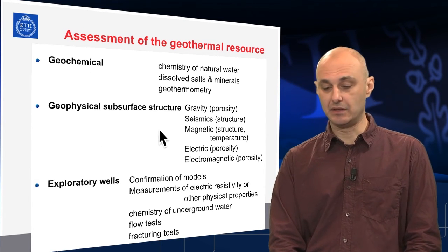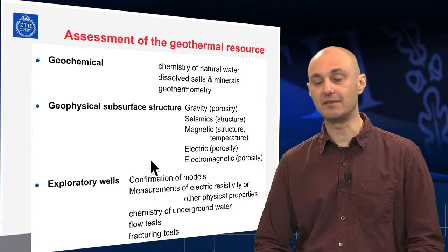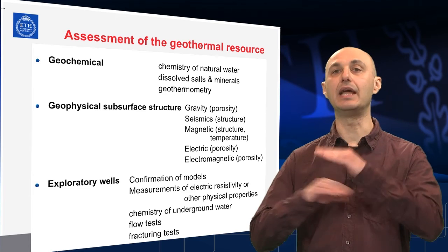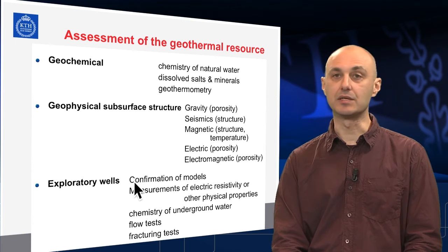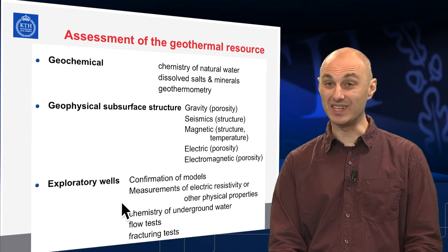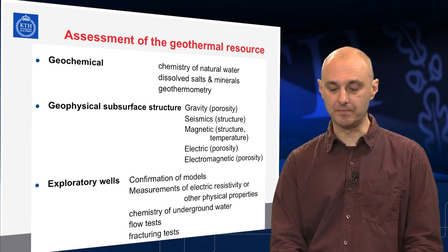The physical inspection of the Earth's surface can be done in several ways again, by the porosity of the soil or the rock beneath it: gravitational measurements, seismic measurements, magnetic measurements, electrical and electromagnetic measuring in different ways, different structures, how the structures are layered beneath the surface, and what they might promise in terms of possible penetration, presence of natural aquifers and so on.